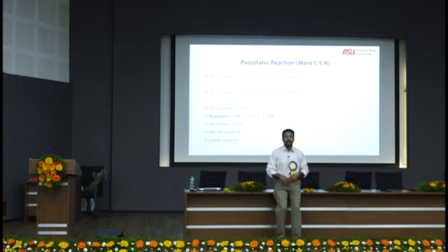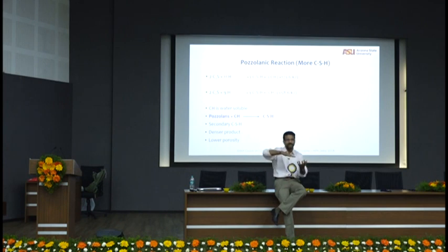There is actually, in northern parts. I was called once for some consulting work in Uttar Pradesh, or Uttarakhand now, Uttar Pradesh formerly. And they have quite a bit of reactive aggregates because of the Himalayan fault. Again, reactive aggregates are because of how the geology is formed. From the Himalayan fault, there were a few places where there was faulting of rock layers through which you're getting a lot of aggregates, exposed cherts and stuff in those aggregates.